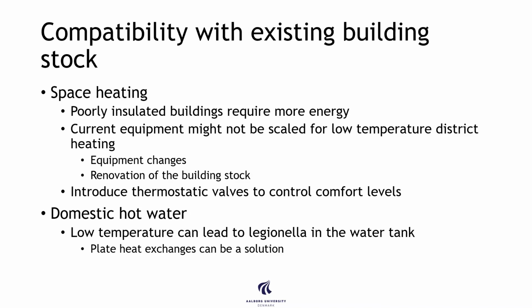So if we look at the existing building stock, when we have space heating, which is one part of what we want to supply with low temperature district heating, there's a risk we have poorly insulated buildings and they require more energy. And right now our current system might not be scaled for low temperature district heating, so we need to make some equipment changes. We need to renovate the building stock. And I think it's a combination, we probably need to do both.